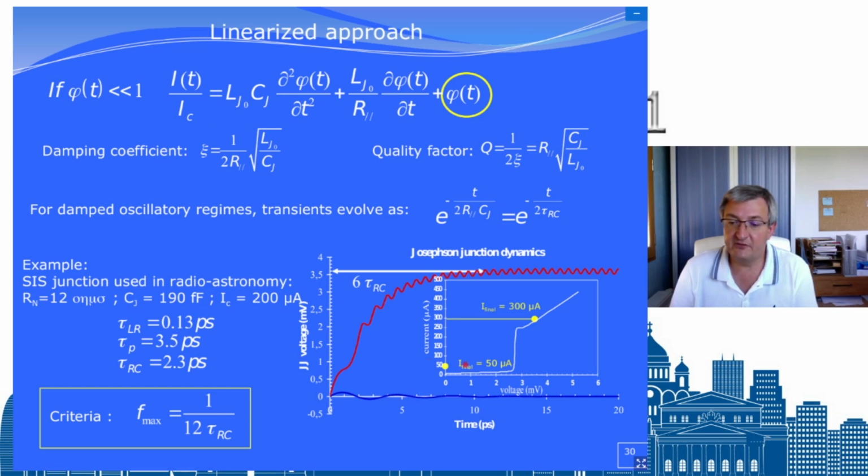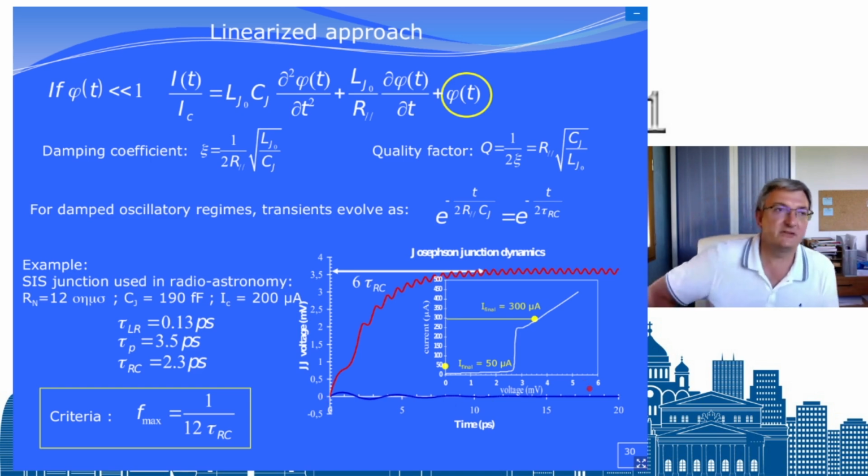And you see that with 50 microamp, the voltage will change because since you change the current, you change the magnetic field, Faraday's law applies, you have a voltage, but there will be an oscillation and it will go back to zero. So you see the average is zero. There is a variation of voltage, but the average is zero. So on the oscilloscope, you see nothing.